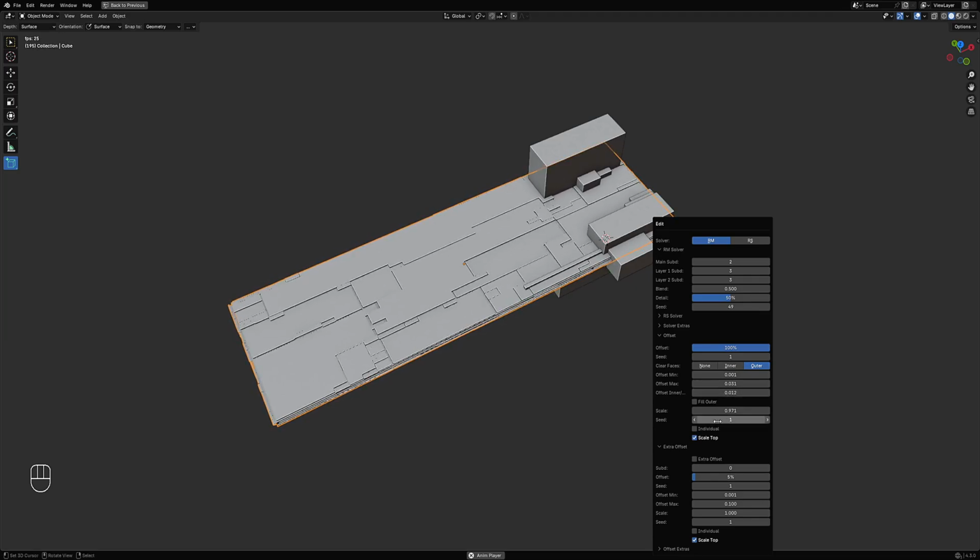And then with the scale, instead of scaling the top, like with none, you scale the top like that. It just scales the top of the extrusion. With this off, it scales the panel islands using the side faces.